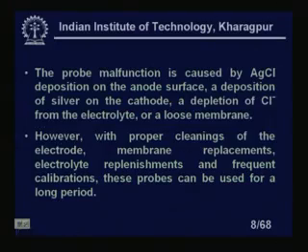We have seen the polarizations, all those things are there. So, it needs repeated cleaning, replacement of the electrolytes, or supply from a permanent reservoir. That, and frequent calibrations, will make the sensors usable for longer, over a period of time.